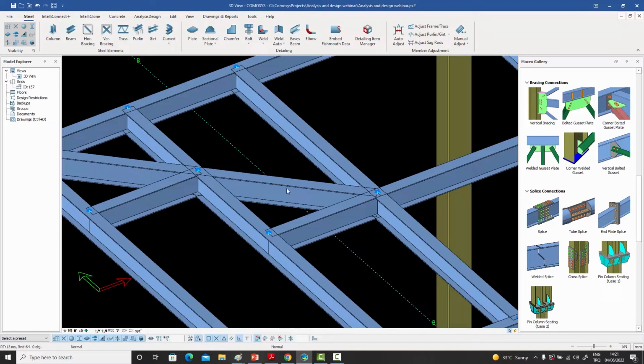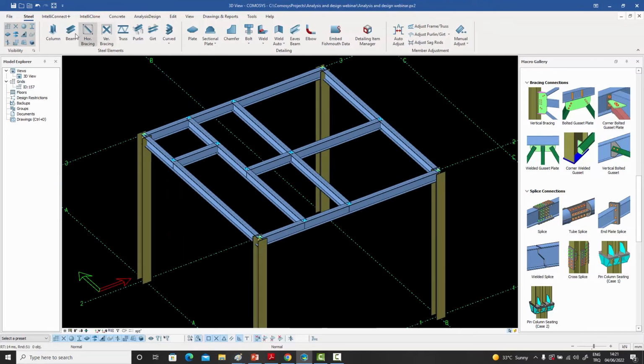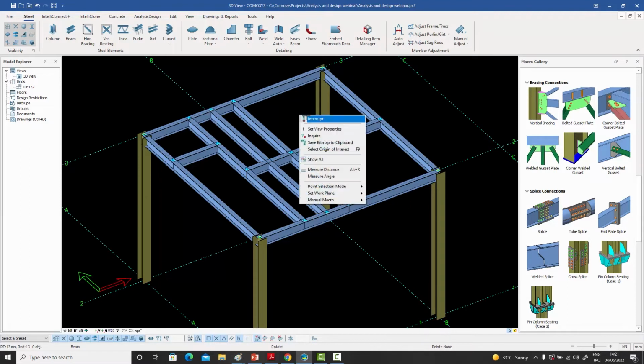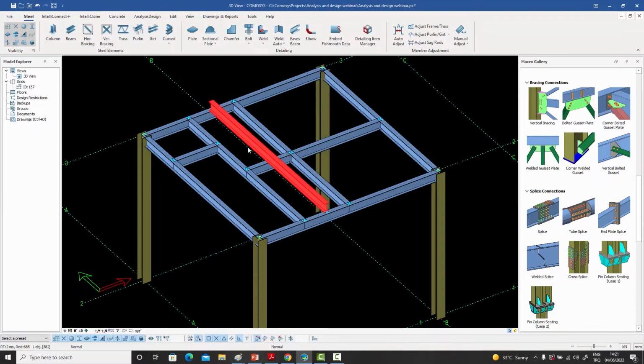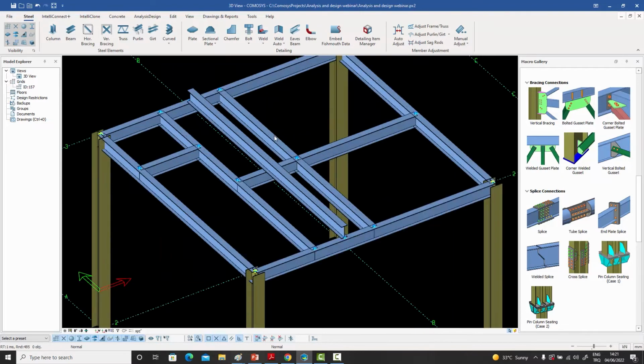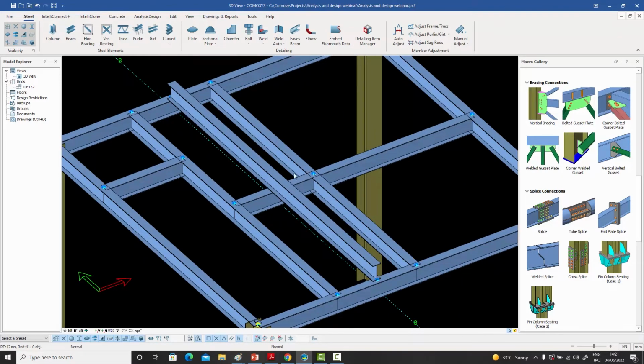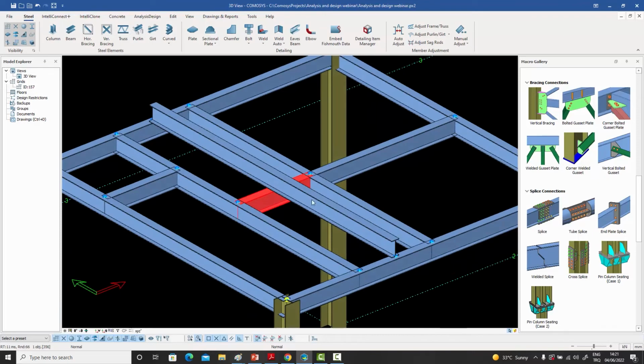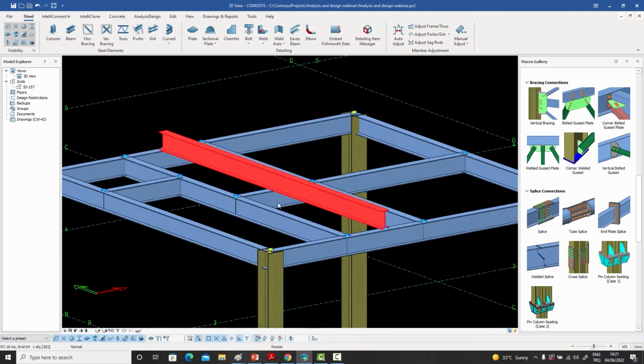Now, that might seem obvious. It makes sense that you shouldn't have two continuous elements going through the same point. Obviously, there'll be a huge clash. But in steel detailing, you can have situations like this. For example, if I were to go to the midpoint from there to there, and instead of putting that behind, if I entered it like that, now this could be a valid real situation in which this beam is sitting on top of these beams, and one beam is going over. So at this point, there is a continuity in both the elements.